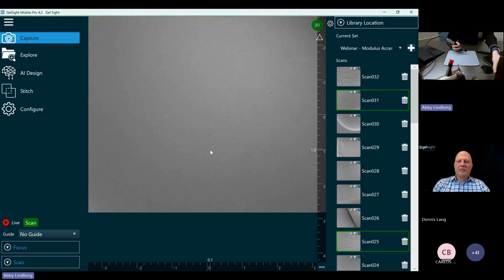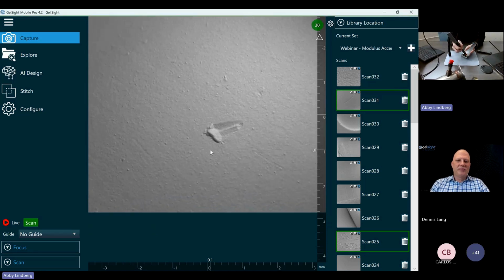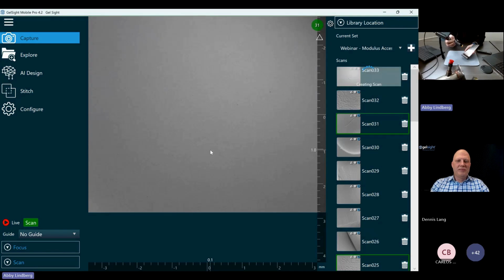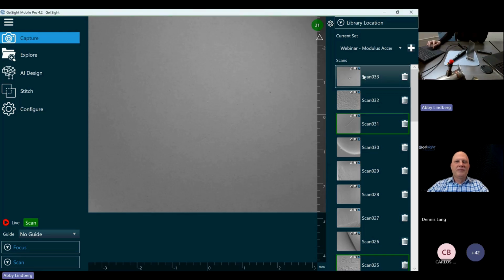And then I'll take our turbine blade and we'll take a look at the defect towards the root here. So I'm just going to press this onto the surface and you can see it pick up that defect. And I'll click the button to take the scan. Just as we've done with all of our other systems, you'll see the software is the same. Our 3D data is generating now. And then we'll be able to open that up and use our same suite of measurement tools.